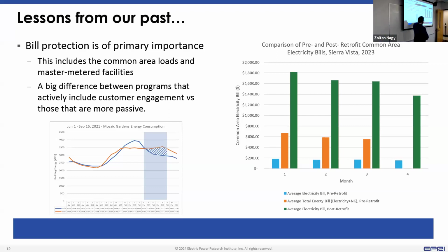As you noticed, especially in the cold months, the reason is that heat pumps are not that efficient in the cold months, right? Your ambient temperatures, even in San Diego, are lower than normal, and the heat pumps we were using are not moderate climate heat pumps. There were a bunch of engineering challenges with this community as well, figuring out how to size the tanks and so on. So there's a whole surrounding set of engineering challenges that go with it.